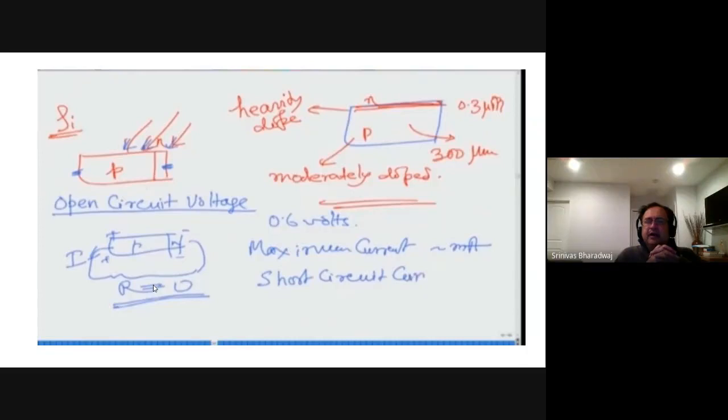Typically the very thin and heavily doped N type, that part has to absorb as much of the light that is emitted as possible, and then release the corresponding electrons. Now, if that does not happen, if it reflects it off, or if it is lost in some other way, which leads to heating, etc., or if it is reflected off, that is not useful. Now, when is it reflected off? It's reflected off when it comes at an angle.